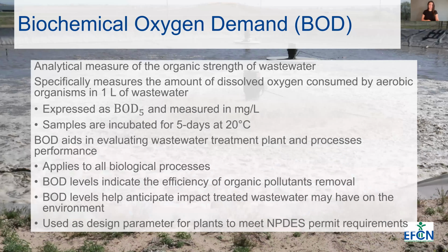We mentioned this a second ago, but BOD is a measurement of the organic strength of our wastewater, which means how much oxygen may be consumed by the microorganisms in the wastewater as they consume the organics. When we're talking about BOD for wastewater analysis, it refers to the specific measurement of the amount of dissolved oxygen consumed by aerobic organisms in 1 liter of wastewater.